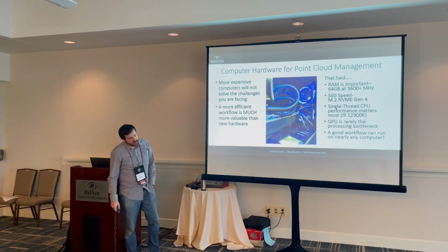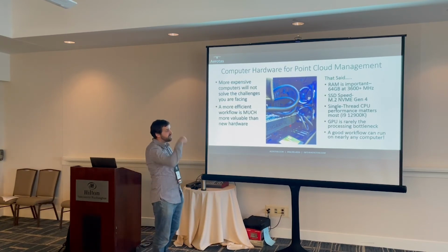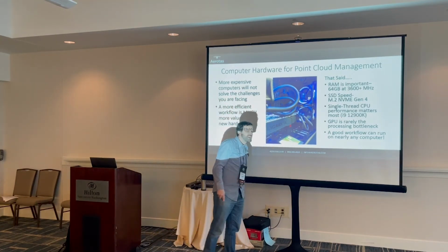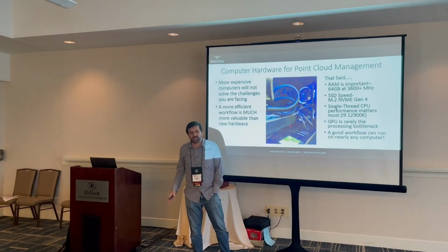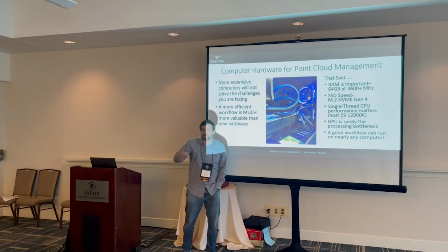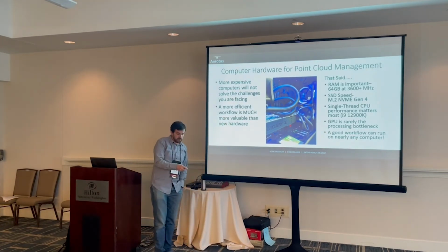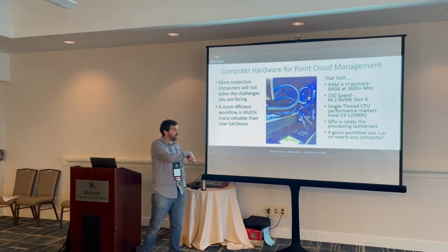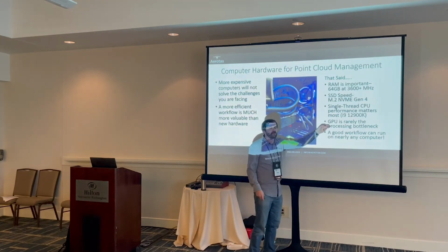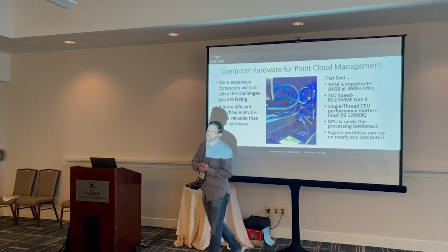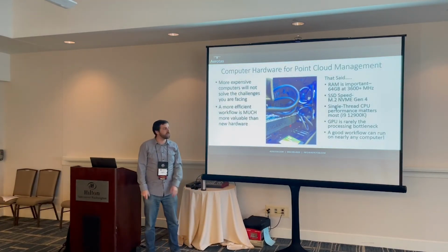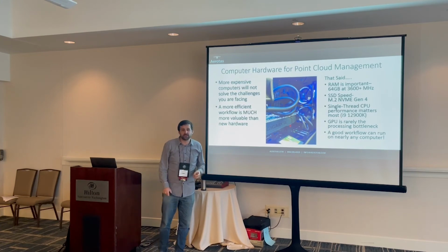That said, RAM is going to be important. Having at least 64 gigs of RAM, particularly for large projects. Having a high-speed hard drive, again, is there. Depending on the software you're using, a lot of the LiDAR softwares are actually bound by single-threaded CPU performance as opposed to multi-threaded CPU performance. If you're a computer geek, that means your actual Intel i9 processors are going to be the most powerful. And like before, your GPU is actually rarely the processing bottleneck just due to the computer architecture here. So again, 64 gigs of RAM and your high-speed hard drive is going to be important, but a good workflow can run on nearly any computer.